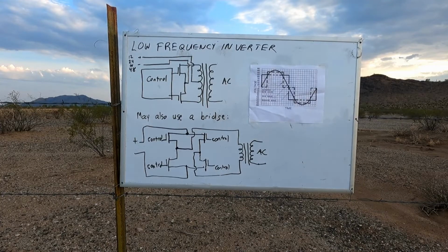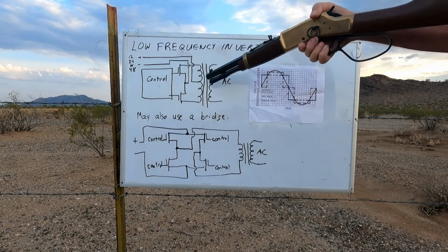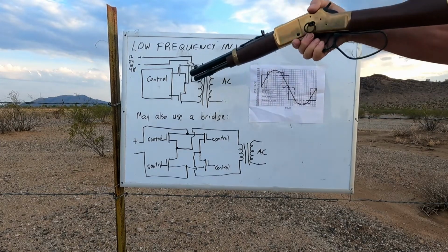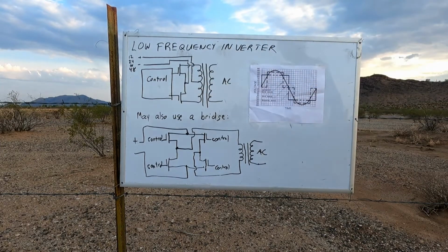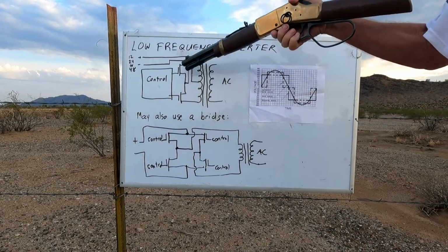Let's discuss some basics of how inverters are architected before we get into discussions of transformer, transformerless, low frequency, high frequency, and whatever. Low frequency inverters were the first technology for inverters that was ever out there, and it was your basic transformer output technology with a couple of power devices. And when I talk about power devices, they might be MOSFETs, IGBTs, a whole host of different technologies, which is totally irrelevant, actually. So there's always a couple of power switches in the circuit.